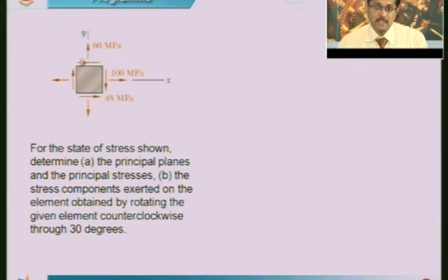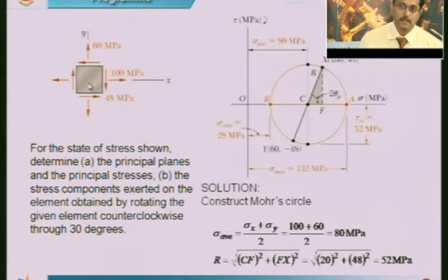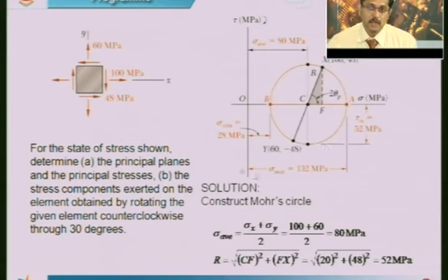Now, look at the shearing stress axis. The shearing stress acting on this plane, which corresponds to sigma x, would make the body rotate in the clockwise direction. So, it has to be positive, and this one, which makes the body rotate in the anti-clockwise direction, should be negative. Let us look at this. What we have got here is the Mohr circle.